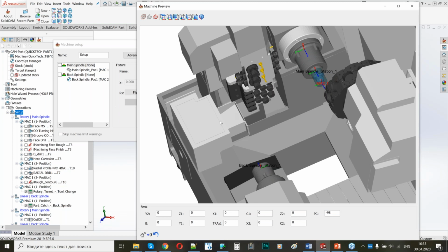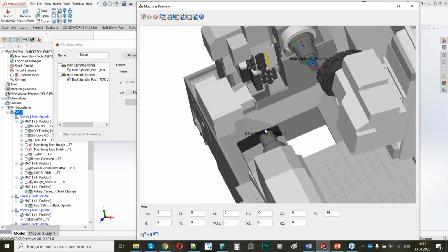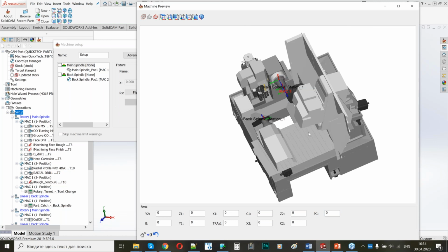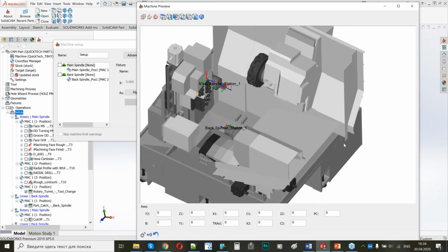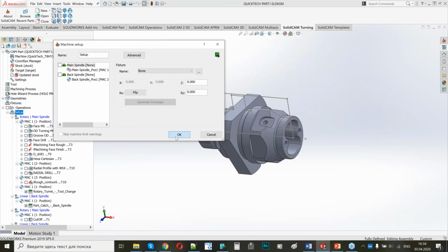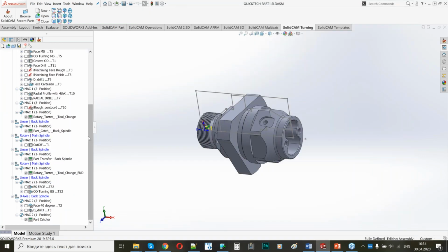The spindle goes here, the catcher opens, and the spindle is unclamping, and there is a pusher inside which pushes the part here, and then it goes back, and the conveyor for the parts turns on, and then you will get the ready parts out of the machine, and in this time the machine is ready to cut a new part. So this is a very important thing. The machine should know the moment when it should drop the part.